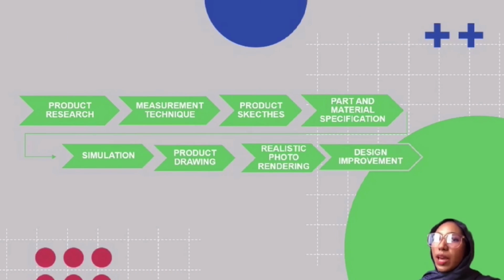This will help to make prediction on motion. However, we have faced some problems in simulation, such as mesh failed problem. So we need to reduce the mesh size to a very small mesh density to solve our problem.